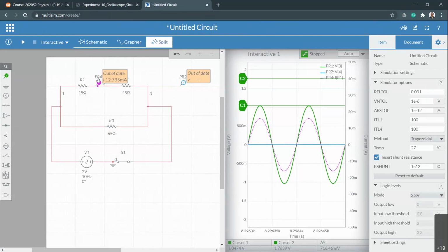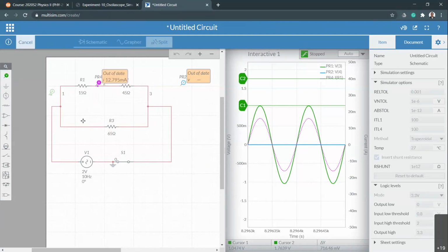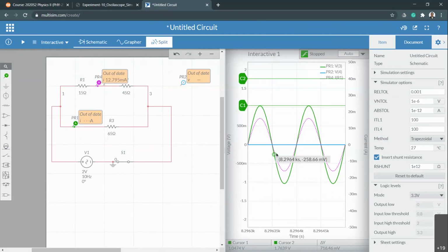And then let's measure current. So the current across this resistor R4 is already, I have a sensor, and then I need to have another current sensor to get the current across the other one right here. Let's put another current sensor there. All right, now those two will give us the current. Now, when you measure the voltage, you can change to two sensors, because otherwise there are going to be many waves on your oscilloscope, which is not really easy to observe all of them. Let's measure two current sensors and two voltage sensors.